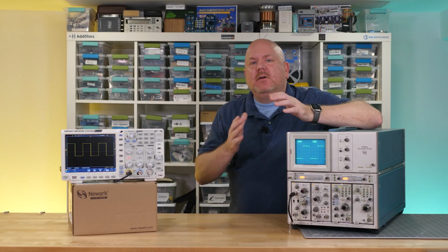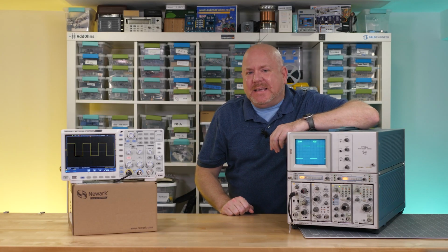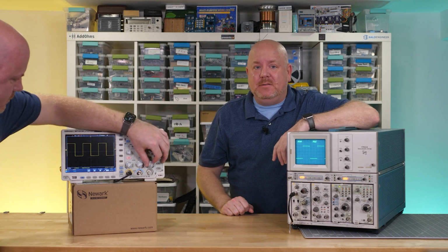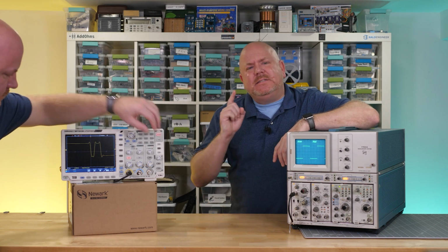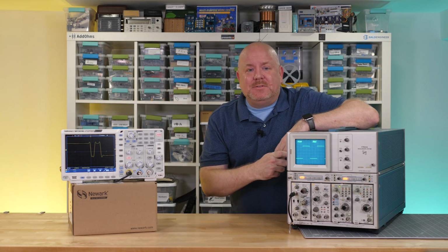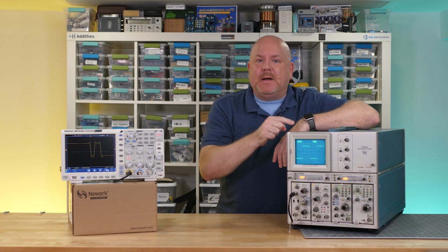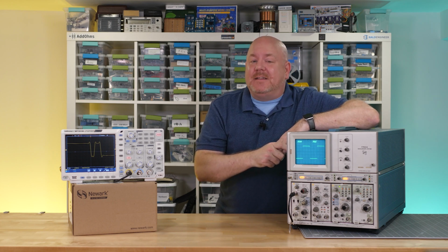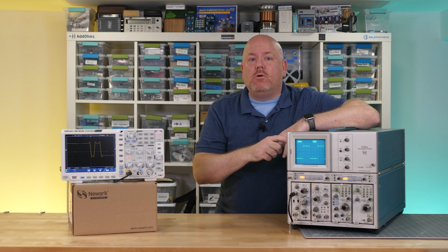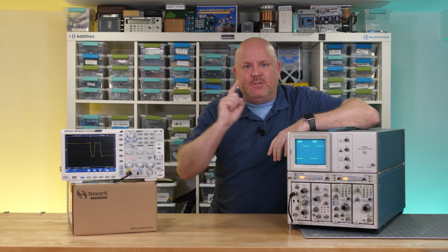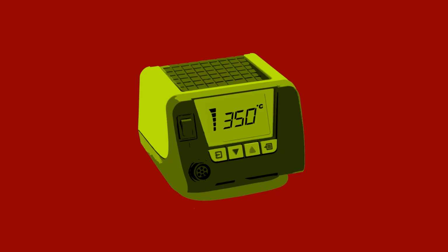When using a modern digital oscilloscope, it is so easy to zoom into a waveform. All you have to do is hit stop and then change the time base. But did you know that this capability has been around since like the 70s? We're going to use my favorite oscilloscope in my collection and take a look at delayed time base, or the origin of zoom and enhance. Wait, not enhance, just zoom on oscilloscopes.